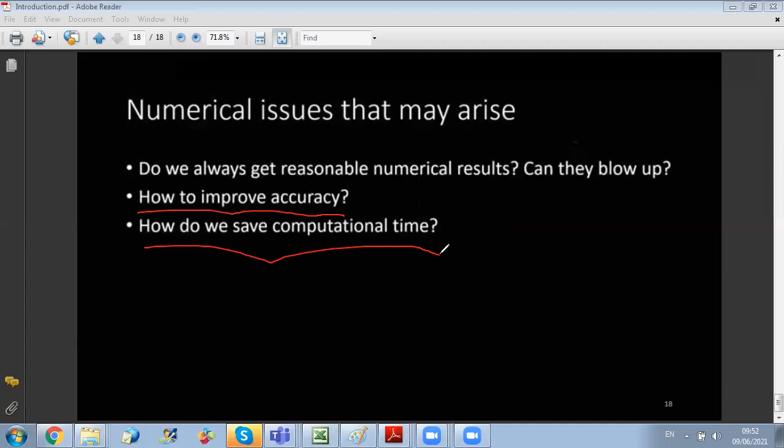For example, if you take an office space with more than 2 million elements, it can take you 1 week to get the temperature and velocity field, which is not very acceptable. If you want efficient solutions, your research time is very important. So you should select the appropriate parameters that will give you accurate results and save computational time.